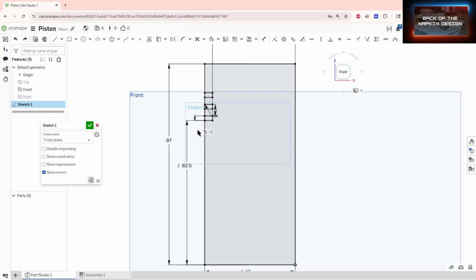Now we need to build a shape that comes inboard. And actually 38 millimeters from here, we're just going to put a line, kind of like a reference line. D for dimension, 38. So this shows us our reference line of that thing that's going in there, the piston rod. Now the diameter of that rod, 20.